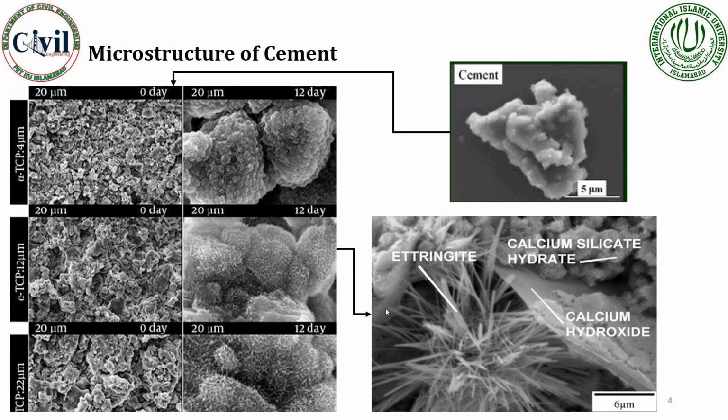The bottom line of this lecture is basically that the higher the fineness, the higher the reactivity. Lower fineness means it might be due to some storage issue. You have humidity at the storage of a cement in which it gains the humidity and starts reacting before the bag was opened. So it can cause quality issues in construction, and it can hinder achieving the desired strength of a cement.